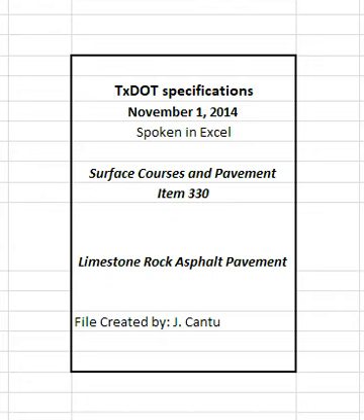Use tamps to thoroughly compact the edges of the pavement along curbs, headers, and similar structures and in locations that will not allow thorough compaction with the rollers. The engineer may require rolling with a trench roller on widened areas, in trenches, and in other limited areas.